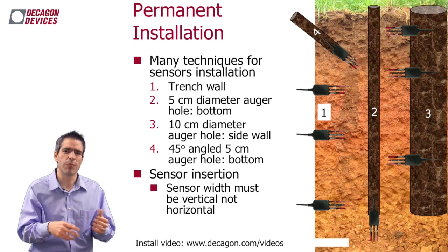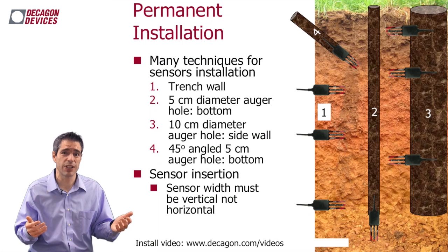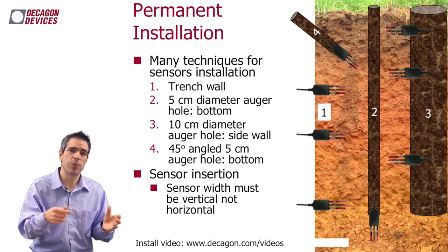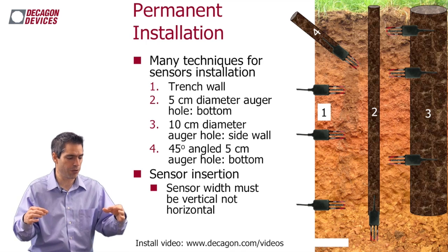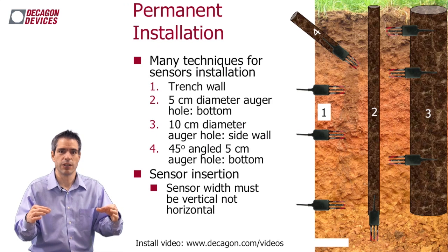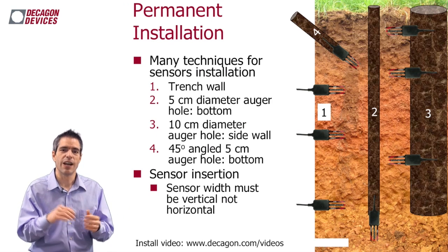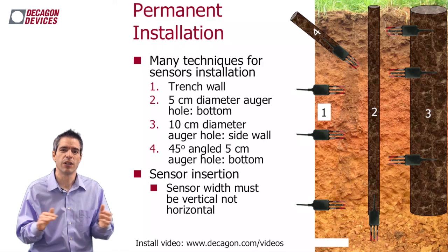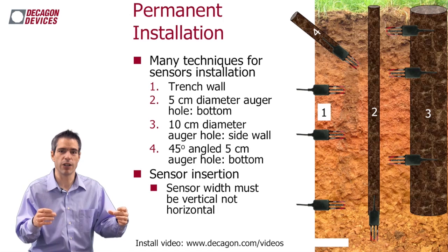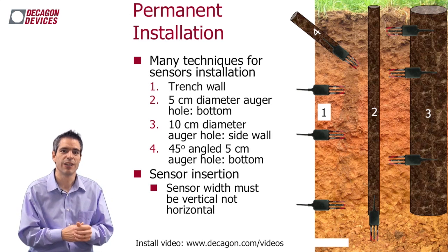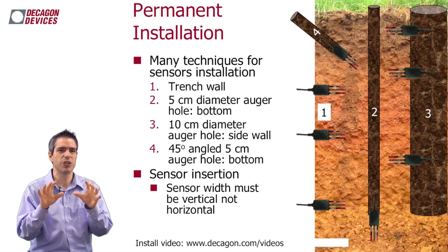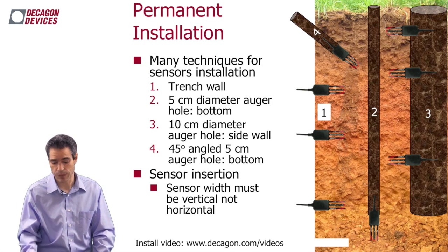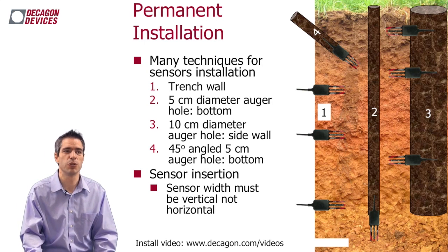Went out, dug up my sensor, and while the top of the sensor looked great, it wasn't ponding water as you might have expected. As I picked up that sensor, an old, flat, long sensor like this, a worm had completely excavated the entire lower soil area underneath the probe, and it was just sitting in air. So that's something for you to think about as you install sensors. Use a little common sense. I didn't. That's just a little help for you as you're doing it.